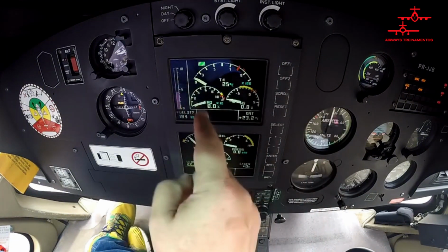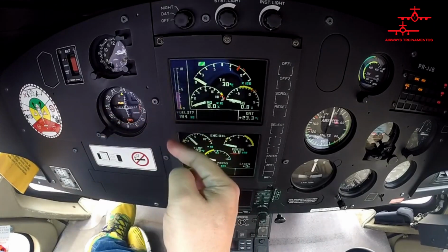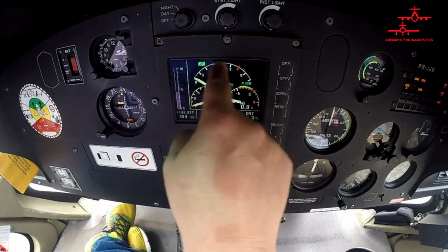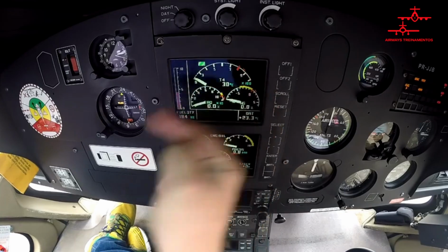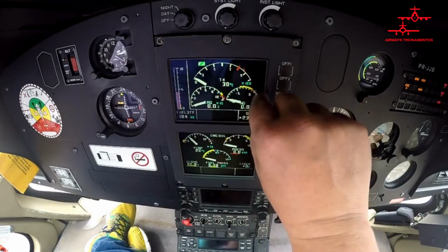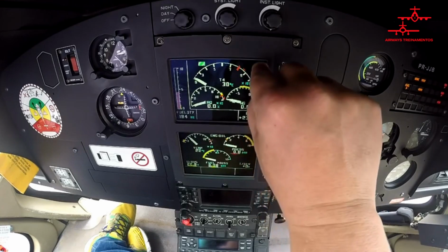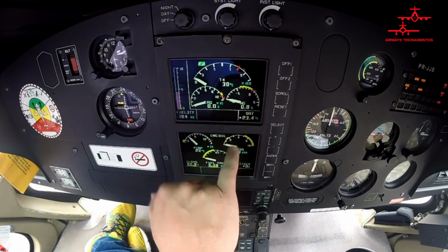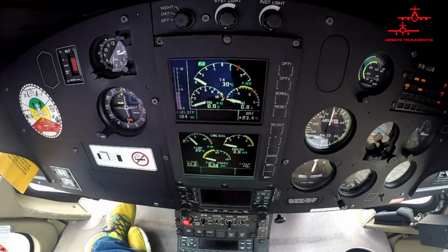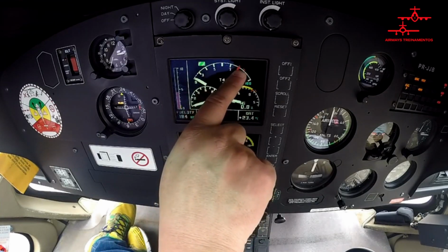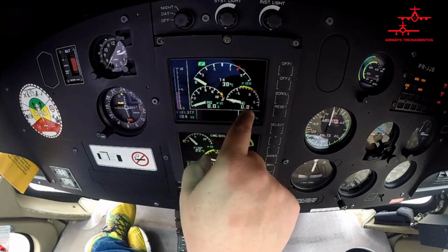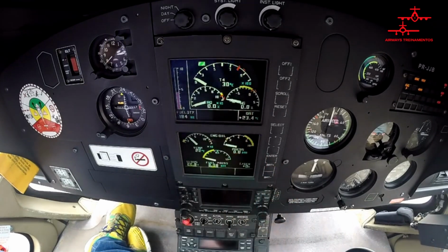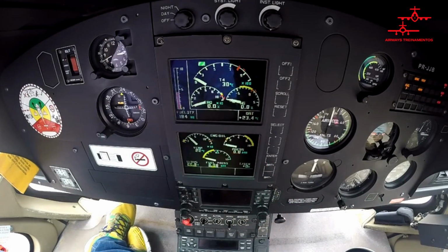In other words, the moment the pilot starts the engine and the NG exceeds 60%, these indicators become a single indicator called FLI. But the pilot has, here on the right side of the screen, all the information for the parameters separately. When the pilot enters the red range, the red bar always appears. Or if he enters the yellow range, the yellow bar appears. If the pilot enters the red range, in addition to the red bar flashing, he will hear an audio signal, a gong, drawing attention to the fact that he has entered the instrument's red range.